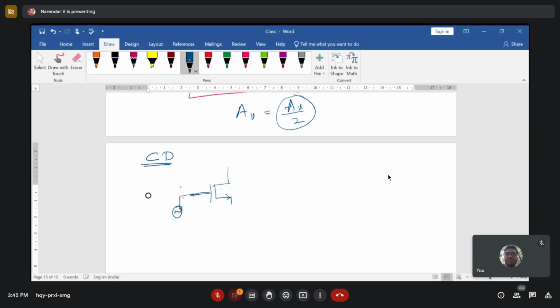So what you have to do is consider V input, where biasing is applied and connected to ground. This is your VGG that you apply. And this drain terminal is straight away connected to ground. Here you have the current called ID, but the source terminal is not directly connected to ground. There is a source resistor, RS, applied, and then we'll tap the output from this RS.